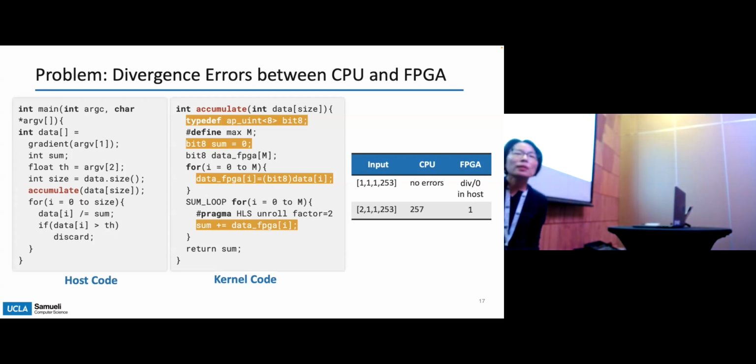Then what FPGA synthesis does is map that directly into a hardware circuit on a programmable circuit called the FPGA. It's almost like building your custom hardware instruction or circuit. So that part is taken into this kernel code, which finally compiles into RTL. But this kernel code is very finite-resource-constrained code.